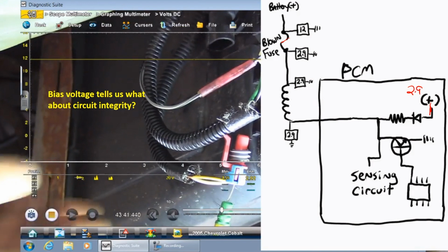It might be 5 volts. I don't know. It could be 5, and that's a super high ohm resistor, and my multimeter is causing the drop down to 2.9 volts. It could be 12 volts as the source, and that's like a 500,000 ohm resistor. The reason I'm reading 2.9 is my voltmeter's dropping it. So you guys understand, I don't know what the source is. I don't care. It is a bias of some kind that is there. Let's call it 2.9 because that's what we saw.